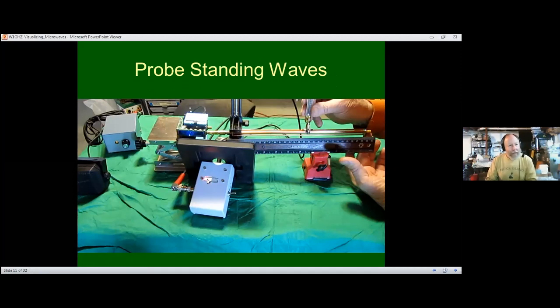Got a little LED bar graph attached to the detector to give relative output. And over here, this is a tone meter, where the frequency varies with the amplitude. So as you get more signal in, that's the DC signal from the detector, the frequency goes up. And we'll use those in a minute.